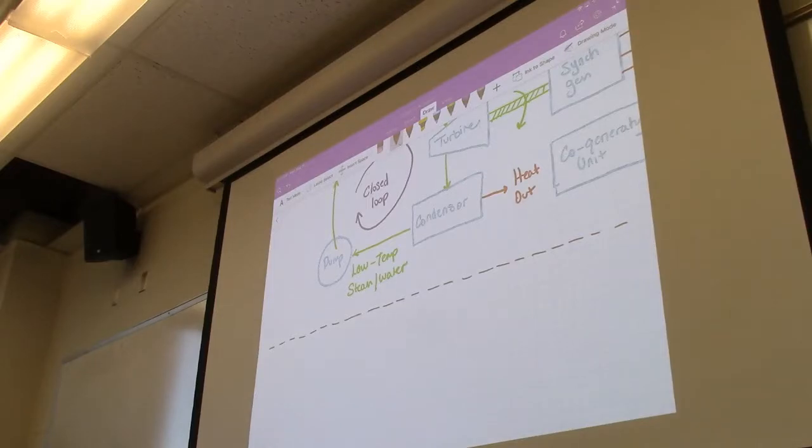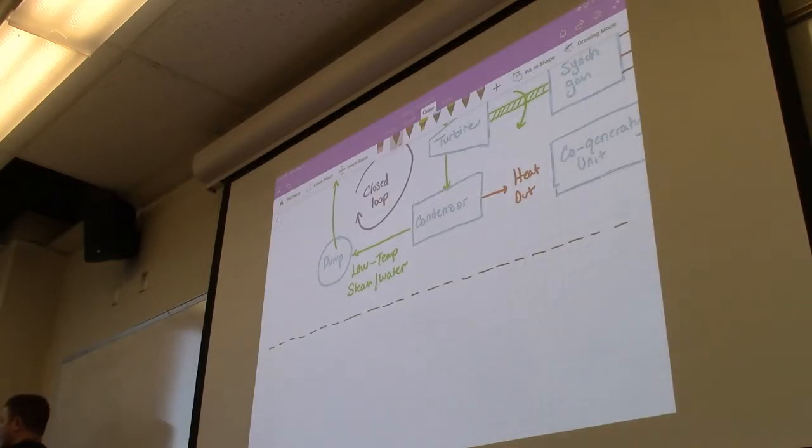And then it makes sense to create the generator itself from a material that has a high permeability and a very small air gap. We want to maximize the amount of energy that flows from the field winding across the stator windings, and we want that mutual inductance to be much, much higher than leakage.